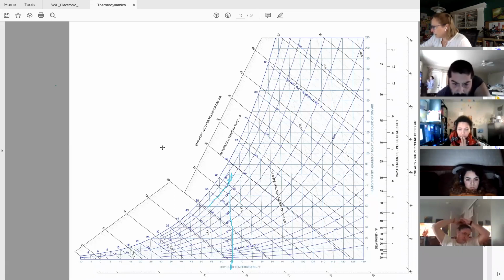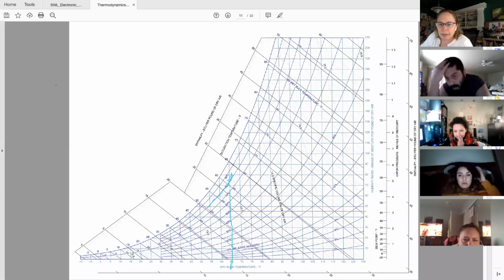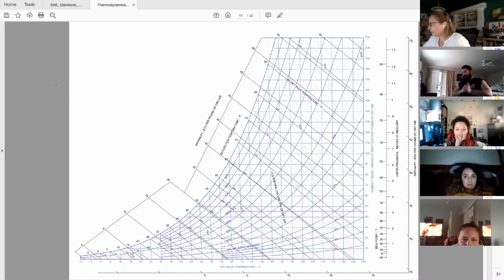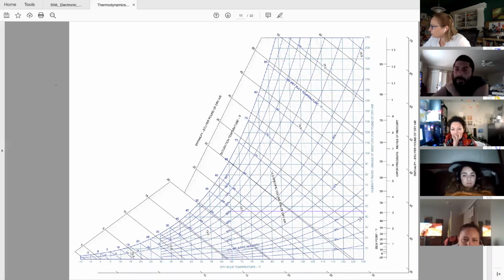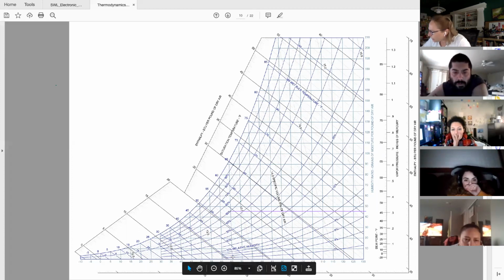Nope, you're a little high. So let's go back. Would it be 50%? Yes. Thanks. I hear a voice. Yeah, so would it be 50%? Yes. Is that Priscilla? Yeah, it's me. Excellent. Thank you. Yes, perfect. So at that moisture content, at 65 degrees, it's hitting the 50% relative humidity curve.